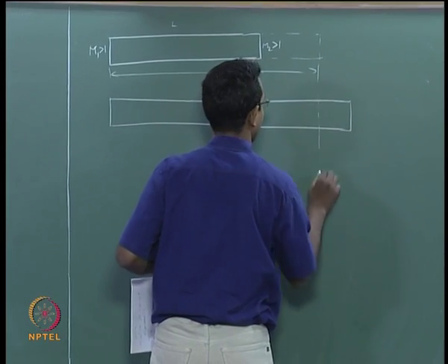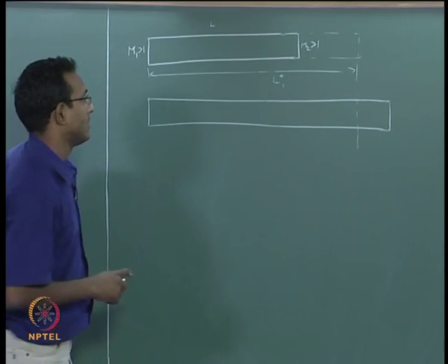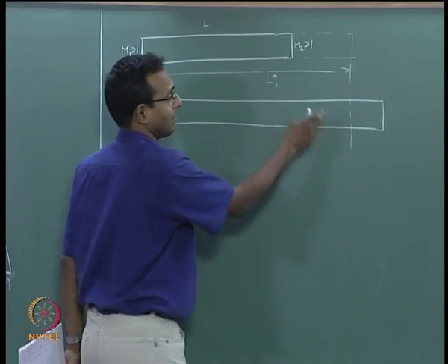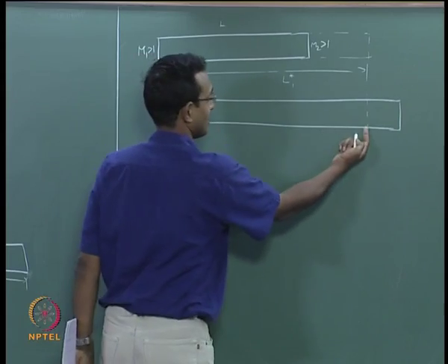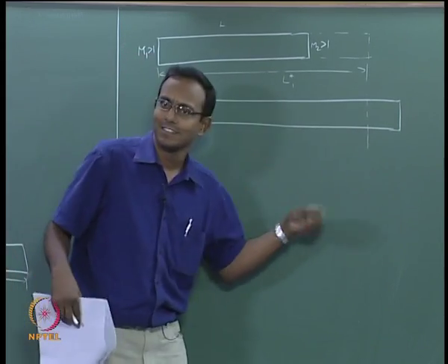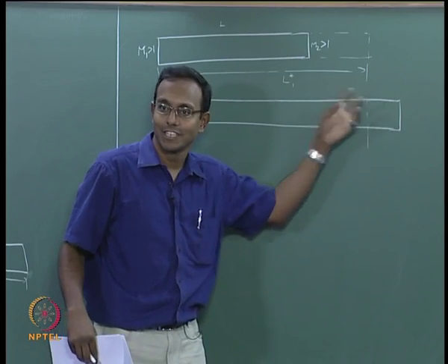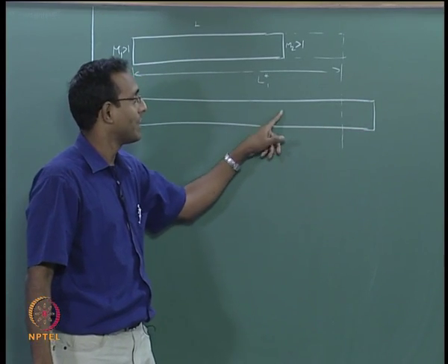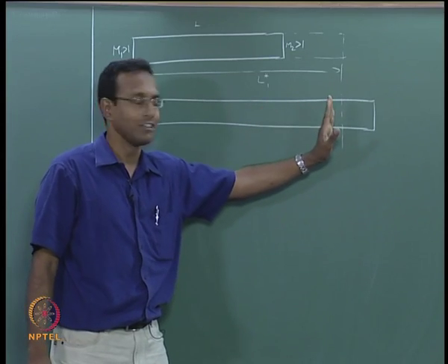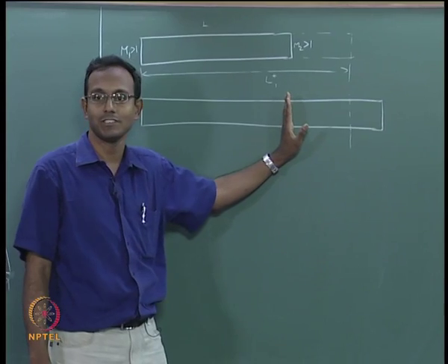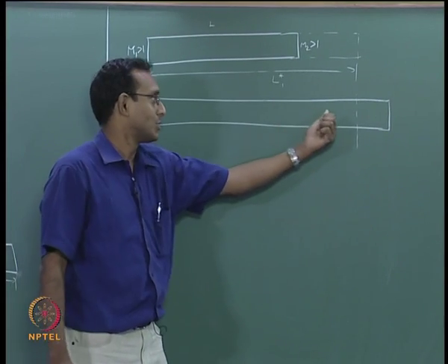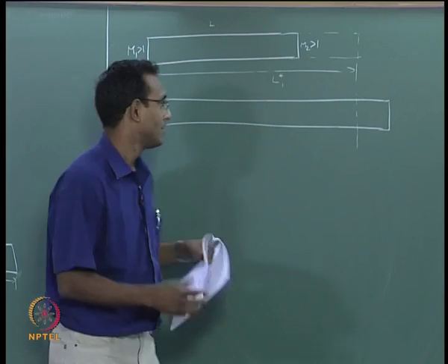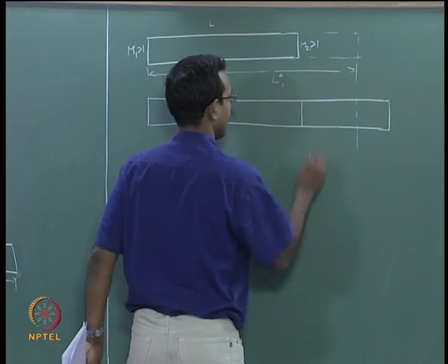Say I am just slightly more than that L star case. If I have this case, then typically there will be a shock. By the way, it will be ahead of this L1 star location. Okay, the shock will always be ahead of this. What is the rationale for that? This extra length is what is going to cause excess resistance, and so that will send out a set of compression waves, and as they come in, they find higher and higher Mach number flow resisting it. So, there will be a point where those compression waves come to an equilibrium against the flow. It is like a treadmill, right? The shock wants to run ahead and the flow is going this way, and it will come and stabilize somewhere here typically. Okay. So, there will be a shock sitting here.